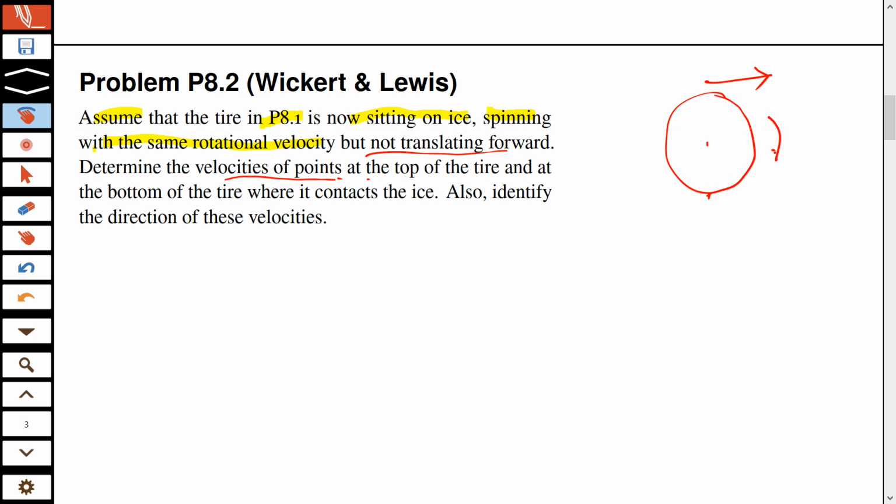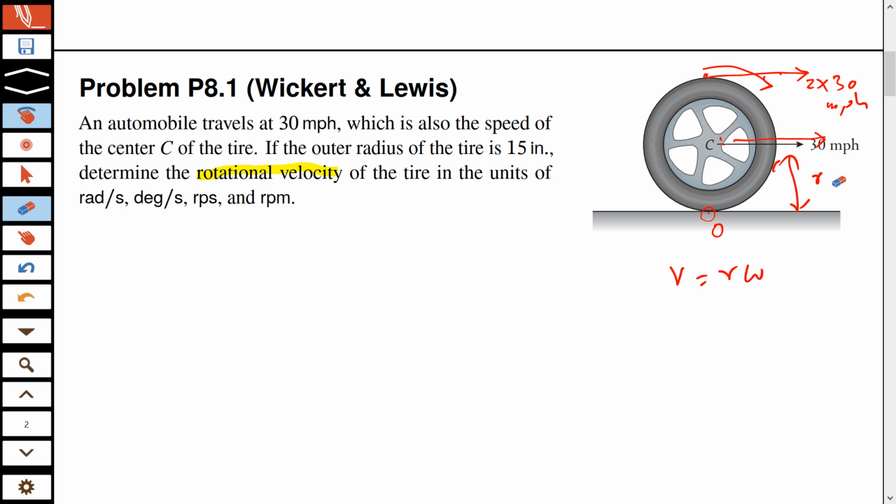Because the rotation is in this sense, this velocity must be... Now this velocity cannot be 0. Why? Because you can go back to that, and basically when you stop, because it's a rigid body, if one point stops moving in a certain direction, every other point must stop moving. So if you set this velocity to 0, you have to subtract it from this point, you have to subtract that from the velocity of that point, and you have to subtract that from the velocity of this point.